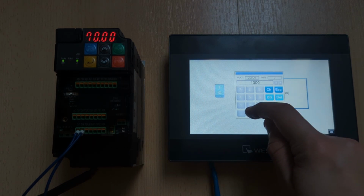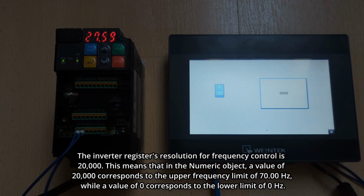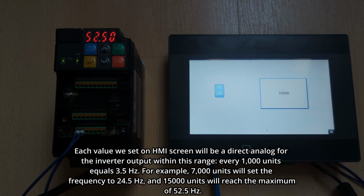The frequency value we can set on the inverter ranges from 0 to 70 Hz, defined by parameters F03 and F15. The inverter register's resolution for frequency control is 20K. This means that in the numeric object, a value of 20K corresponds to the upper frequency limit of 70 Hz, while a value of 0 corresponds to 0 Hz.